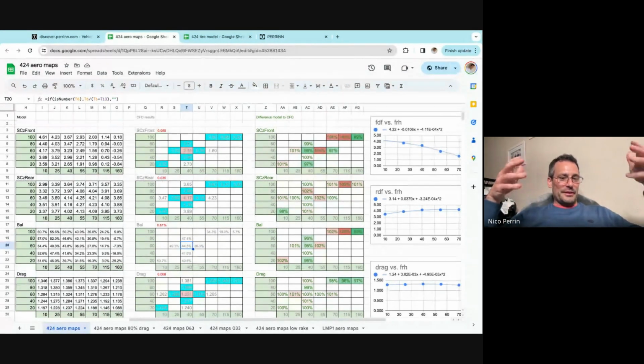And this is required because it's easier to control oversteer in slow speed, but not so much in high speed. So you see how we use aerodynamic balance to give a bit of stability in high speeds. You never would put aerodynamic balance in front of weight distribution or higher.